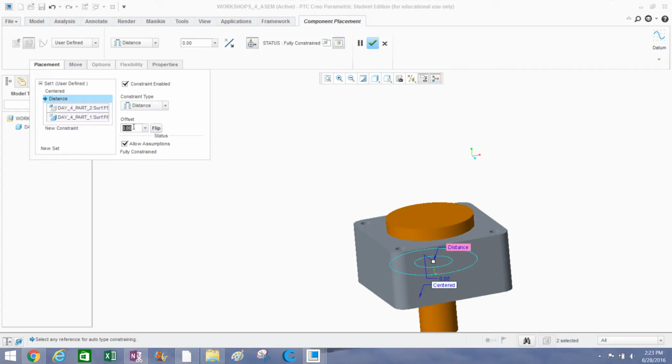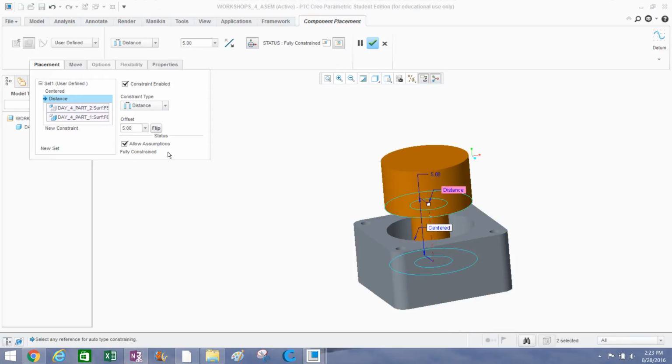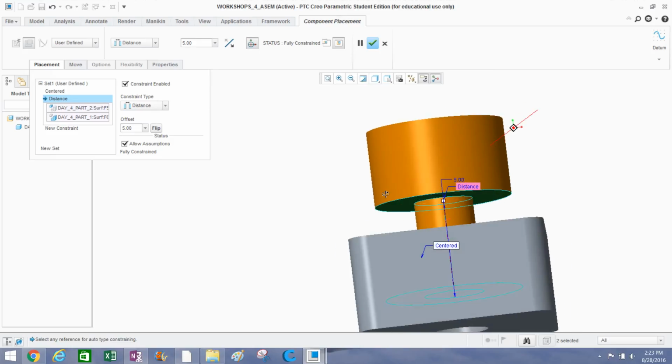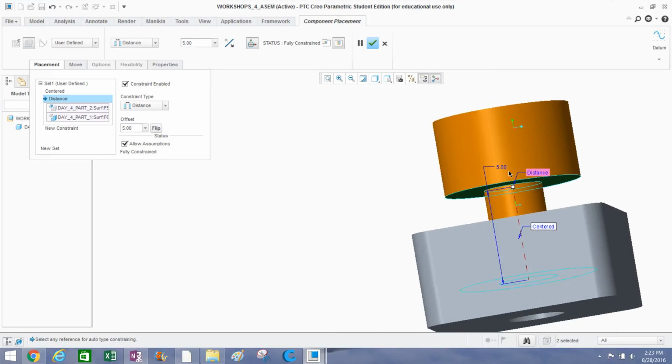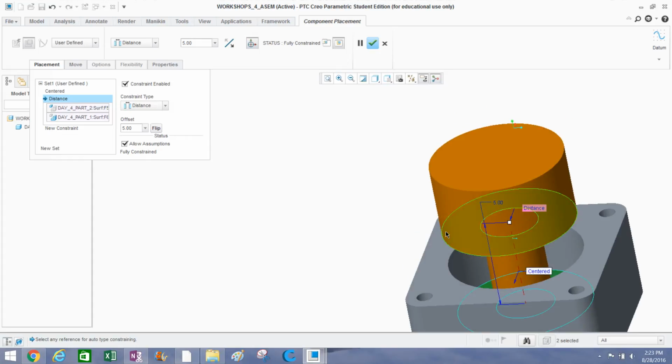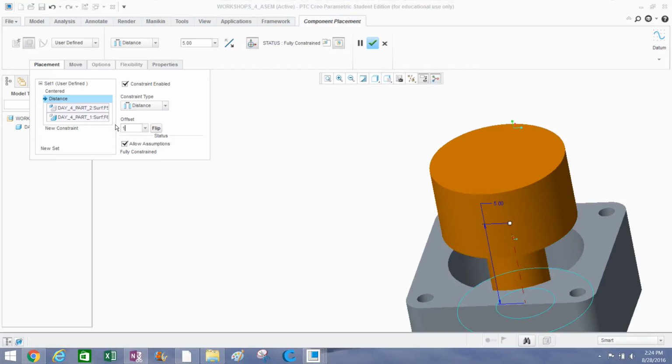So just to show you as an extreme, if you were to type under offset 1, all right, let's try something. You can actually see it move, while the object 5. You'll see that that distance is 5 inches, and you can always see by this little blue arrow that tells you the distance here. I can tell you that the washer that we're installing is 1/16 thick, so you actually set the offset at 1/16. Of course, you can still do math in this, which is really nice.